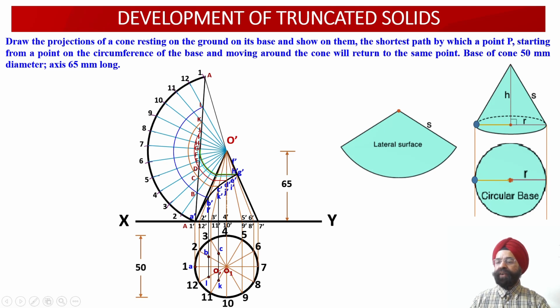So what the observer has to do in order to obtain points D and J over here is look at this particular solid from 90 degrees, that is from the side view. Now there is a definite relationship between height and the radius. So corresponding to these points of intersection D dash and J dash, we know this height. The cutting plane has cut this particular slant generator at this height. So corresponding to this height, we know the radius.